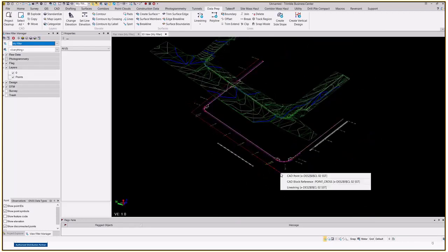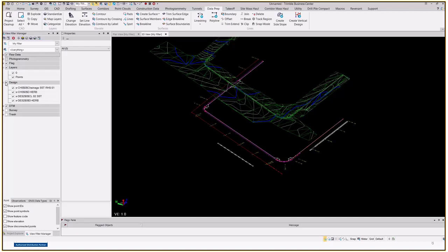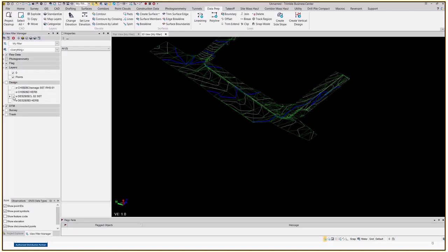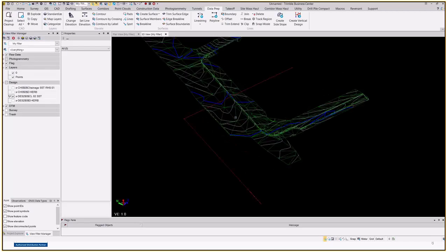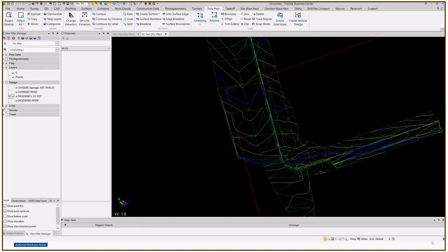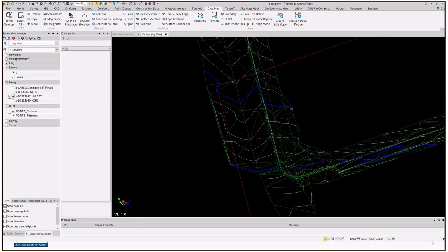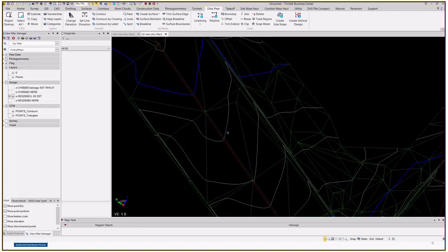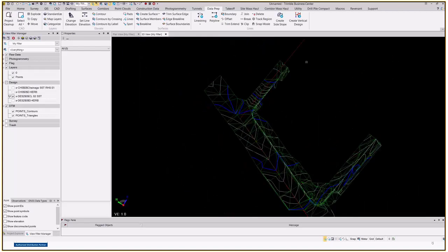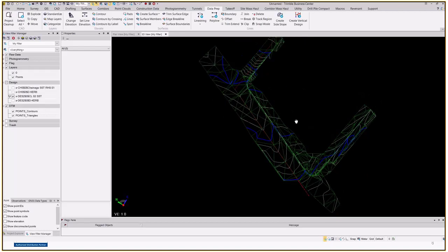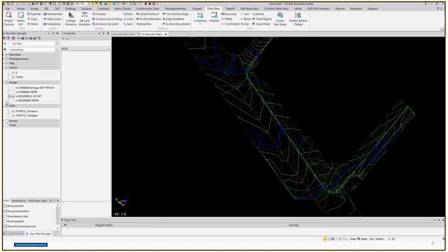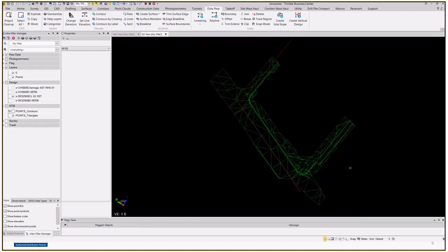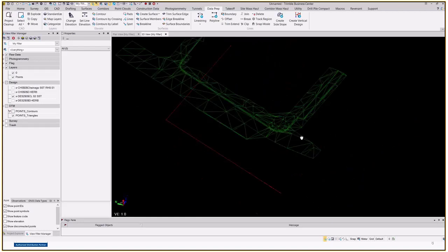We will look at our centerline, so we're looking at X centerline 02 SST, and we will turn everything else off except for that. And then we also have our left on. We have our DTM, so we can turn off our contours, because really a contour is not the best representation. It's a graphical representation of what's there. You can use it if that's all you have to elevate your information, but I have a DTM which is much cleaner, so I'll just turn off my contours and use it. So let's bring up that line.